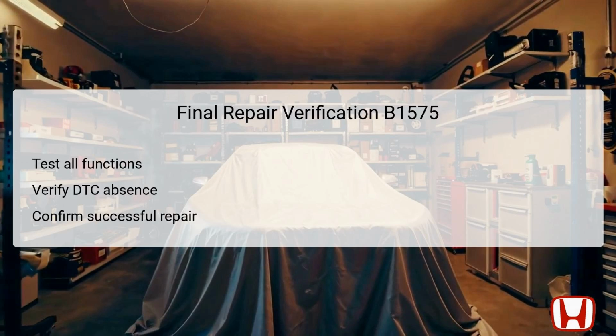After completing the troubleshooting steps and replacements, the final repair verification is crucial to ensure the issue is resolved. Begin by testing all functions of the automatic lighting system, making sure the headlights switch on and off automatically as intended. Then, check the diagnostic trouble codes again, using the HDS to confirm that DTC B1575 is absent.